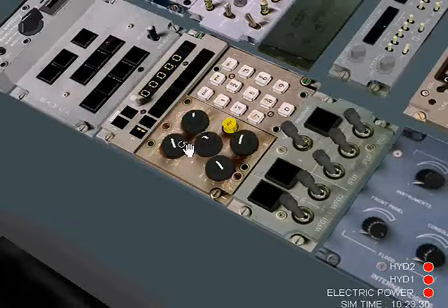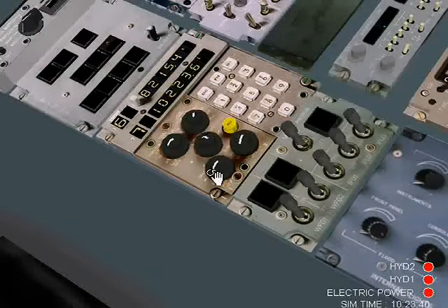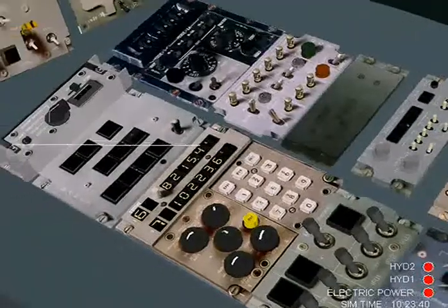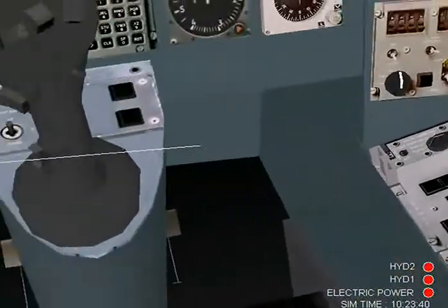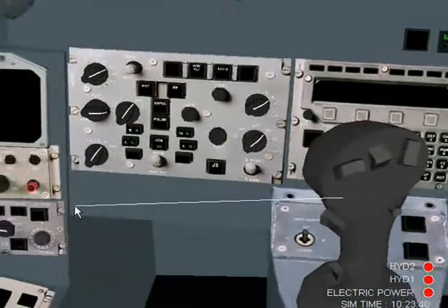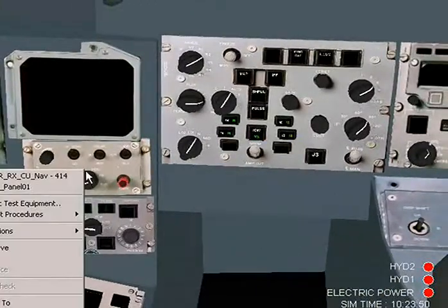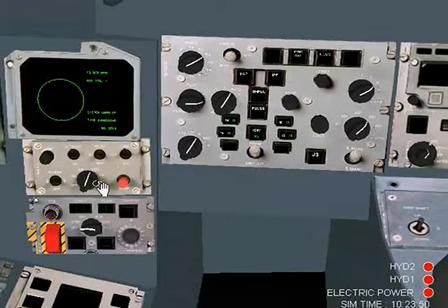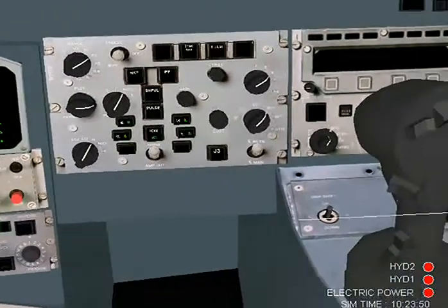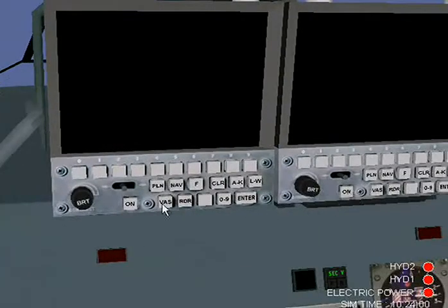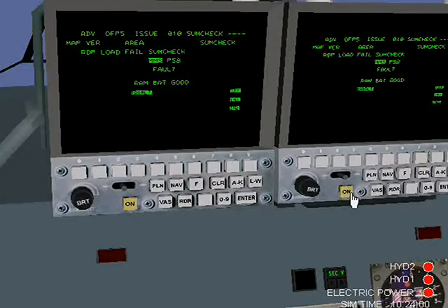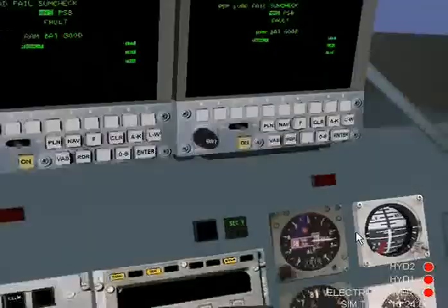As well as knobs, switches and buttons, the LRUs also have working dials, lamps, LED and vector displays, and audio alerts. Notice how they activate as the student interacts with them. The green vector displays accurately mimic the functionality and appearance of the real-life versions and are generated on the fly, as in the real aircraft.